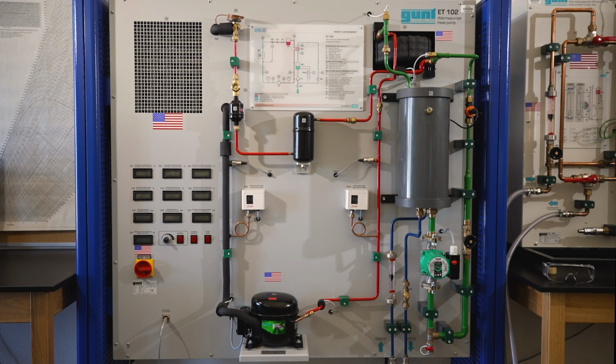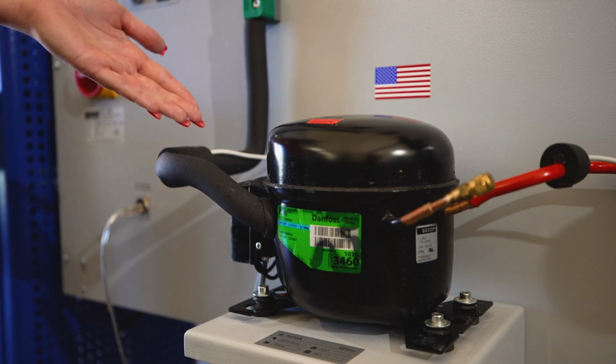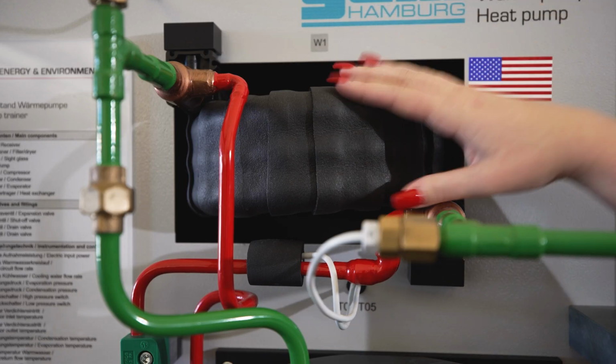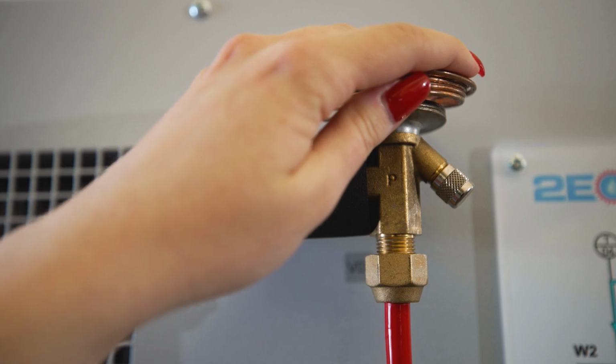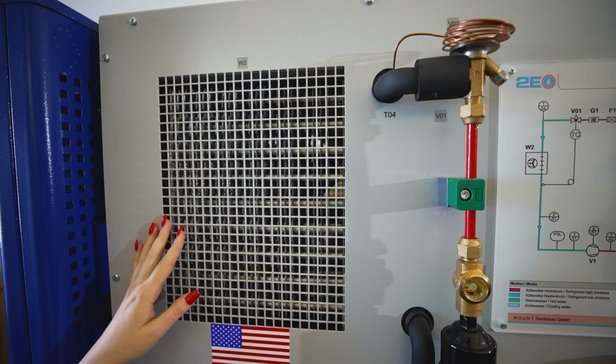The main components of the heat pump are: the compressor, which circulates the refrigerant and increases its pressure and temperature before entering the condenser. The condenser, where the refrigerant condenses as it releases thermal energy to the hotter space or surroundings. The expansion valves allow the expansion of the refrigerant, decreasing its temperature and pressure before entering the evaporator. The evaporator, where the refrigerant evaporates as it takes thermal energy from the cooler space.